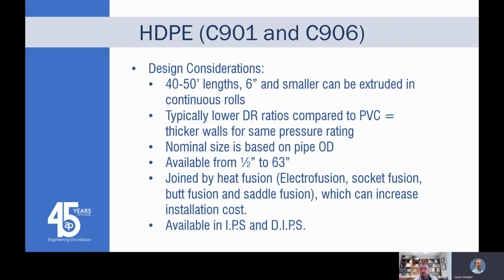Yeah, and I'd add to that, on previous HDPE work where you're coming up above ground, connecting to valves and different things. I'm not sure what we'd have on the municipal side, but if you have some type of valve coming up above ground and you're using HDPE, you have to pay attention to the temperature differences and the forces that can apply onto the piping, and provide adequate thrust restraint, usually with some sort of collar right before it comes above ground so it doesn't pull on whatever you're connecting to. That makes sense. Perfect.